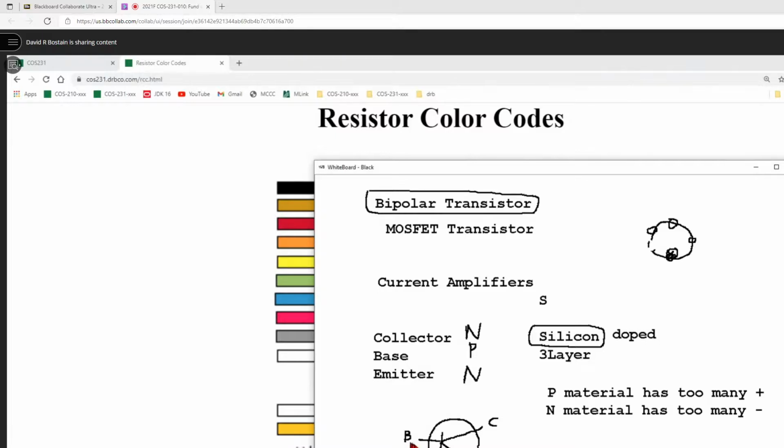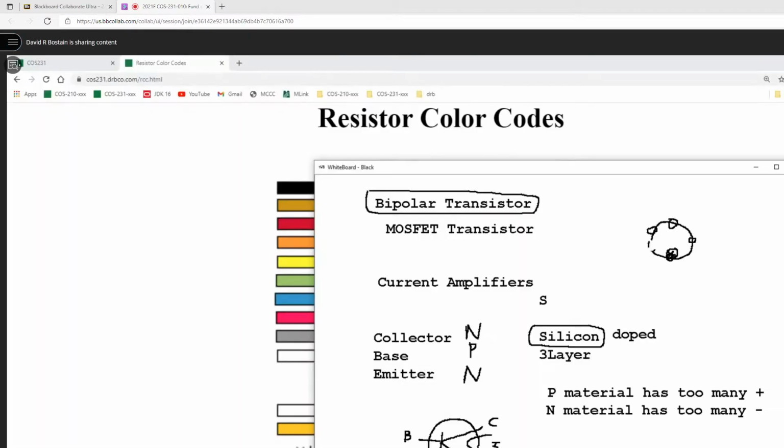We're blocking what's going on by taking these diodes and biasing them so that they are either forward or reverse biased. Now, we're going to talk about the flow of conventional current. In a transistor, a small amount of current from the base to emitter, which we will call IB, will cause a large amount of current to flow through the transistor from the collector to the emitter, electron flow. And we call that IC until it comes out of the transistor.